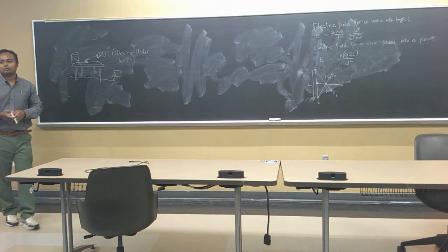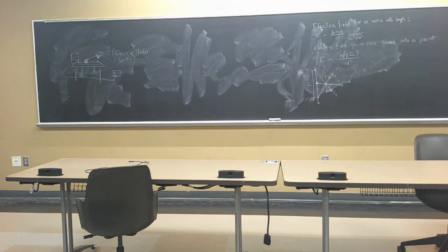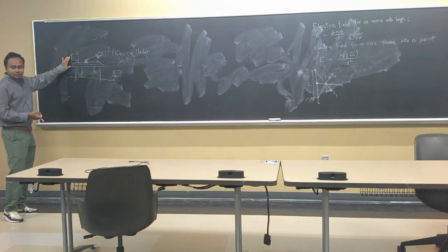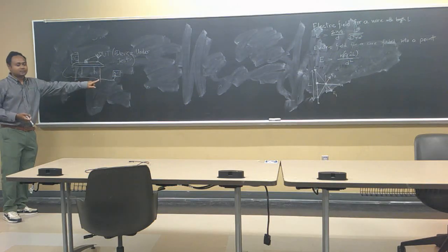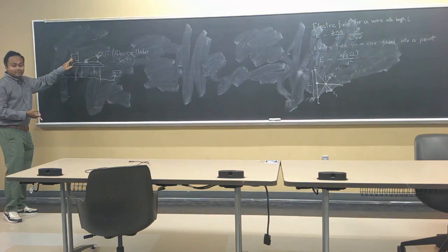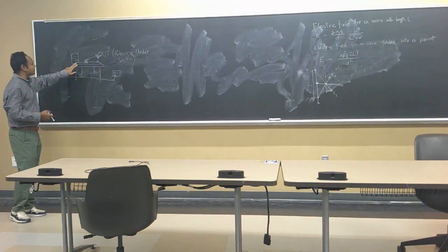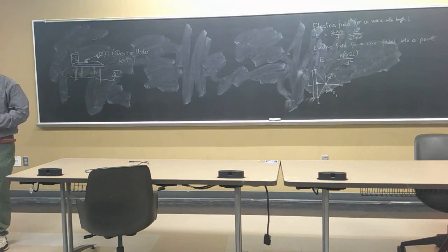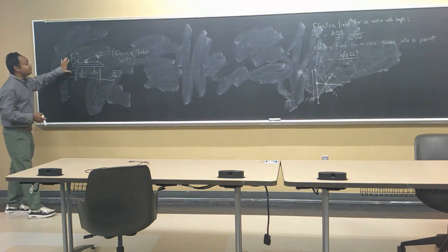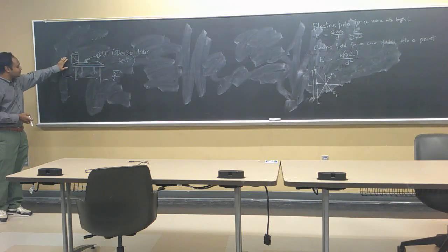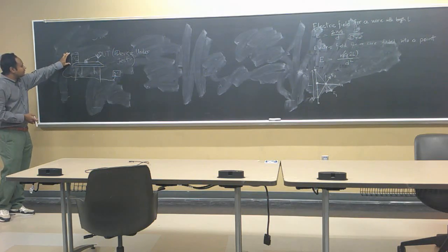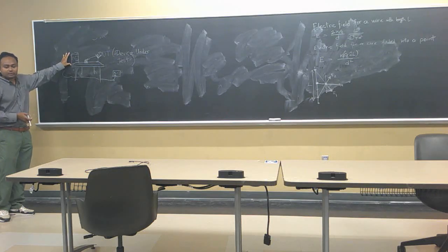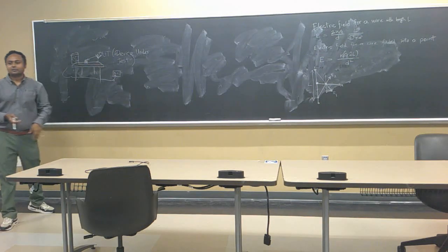And your result is not what you expected. You are getting some disturbance. So you're going to find out what might be the possible source of disturbances. What are the disturbance sources? One source would be the cables, right? One source might be this guy, given that this guy is running, right? If this device is operating, then probably this might also cause some electromagnetic interference. This antenna could be a major source of interference. Okay? So what might be the biggest source of interference that you can think of? Would it be the cables? Would it be this electronic device? Maybe this is a microwave. Or would it be the antenna? What would be your guess?